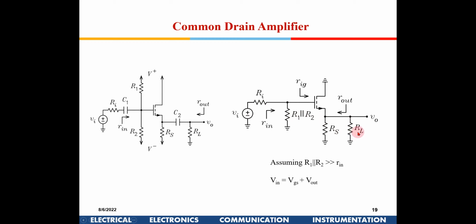Now obviously, power gain means where is the additional power coming from? Actually, that power is coming from the VDD which you are applying. The power is not consumed from the source, it is consumed from the VDD which is applied here. The voltage remains the same, the additional current is very high, and that current is coming from the VDD. So our VDD is the power source. So this is amplifying the power, and that is why we call this common drain also an amplifier. Is it okay with all of you?